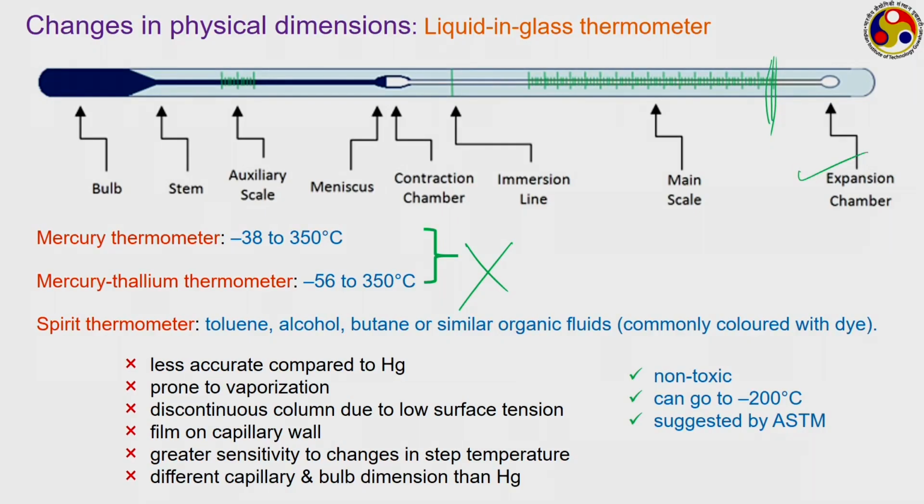Another possible alternative is something conventionally known as the low hazard precision thermometers, or low hazard precision LIG thermometers. LIG just refers to liquid in glass. These can be a replacement for mercury based thermometers. They generally use some non-toxic biodegradable materials, but those materials are proprietary items of the manufacturers, not clearly specifying their properties, but they may be a future option.